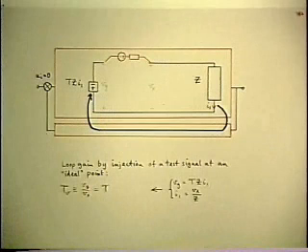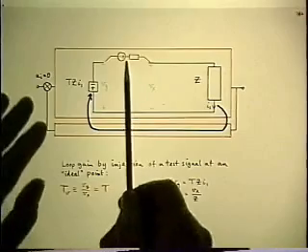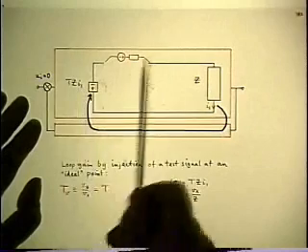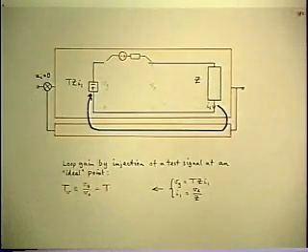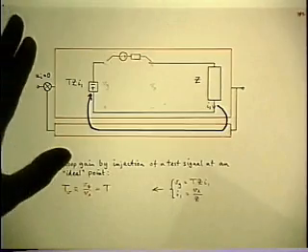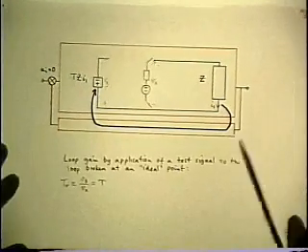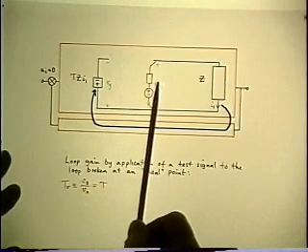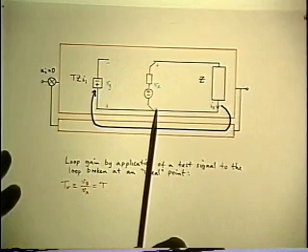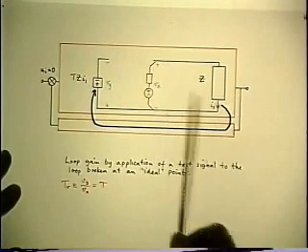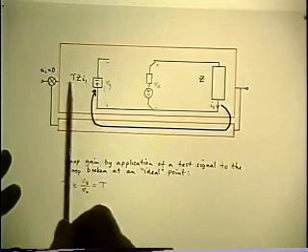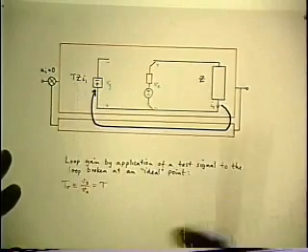I do that to simplify the problem and get rid of all unnecessary things, because the problem I'm interested in is what happens when I can't get to this point. But I've already got the desired answer embodied in the setup of the problem. Okay, just to review the first step, we've shown that injecting the signal into the closed loop at the ideal point also gives the right answer, as well as applying the signal at the ideal point. For the same reason, I1 is Vx over Z. I1 multiplied by Z gives Vy, therefore Vy over Vx is equal to T, and you get the right answer.